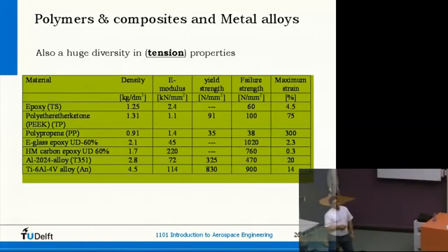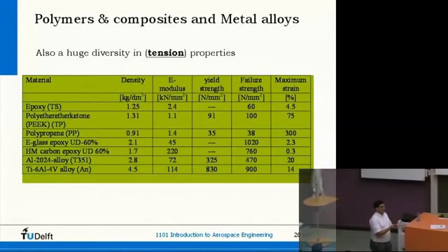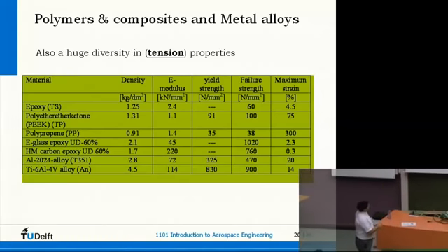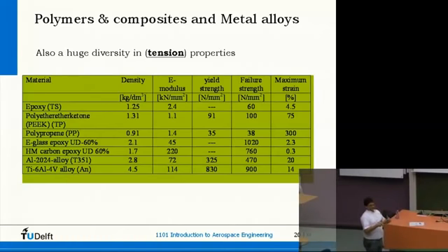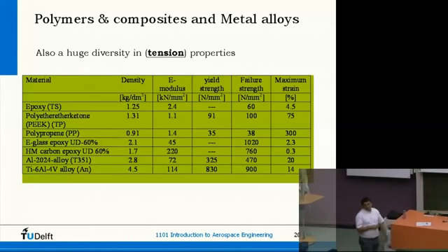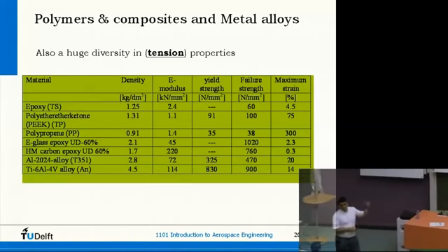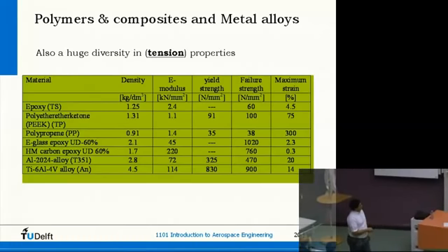60% means the fiber volume content. How many fibers are in there? This is a rather high value. What you often see, for instance, for injection molding or hand layup, you end up with values of 40 or 50%. But it has an effect on the quality of your product. So the higher the volume, the higher your properties can be.